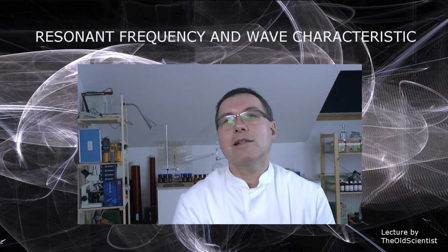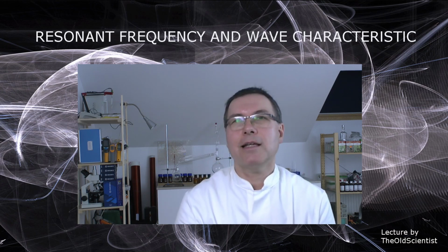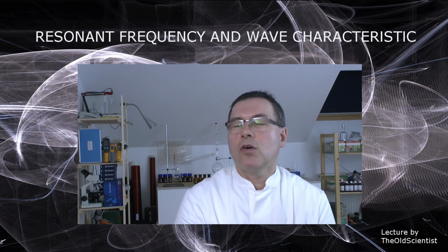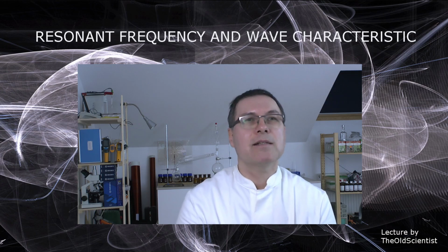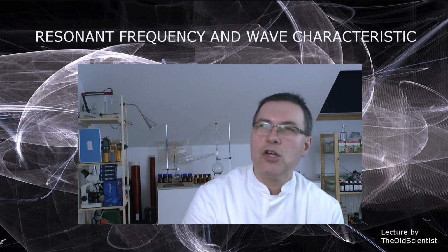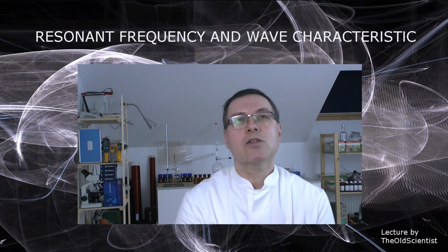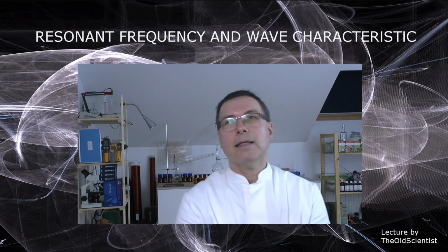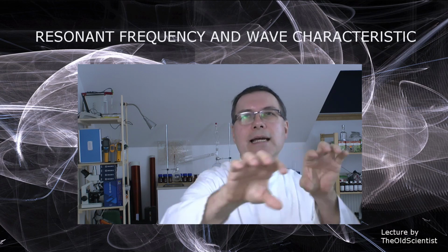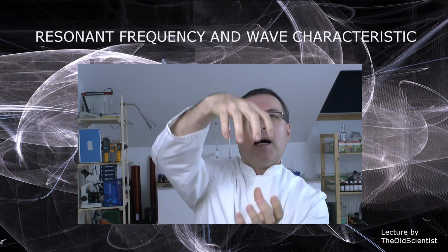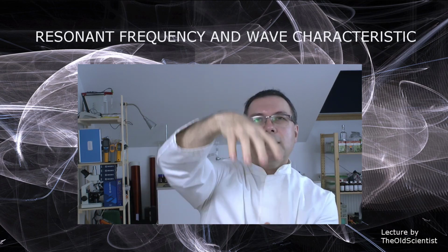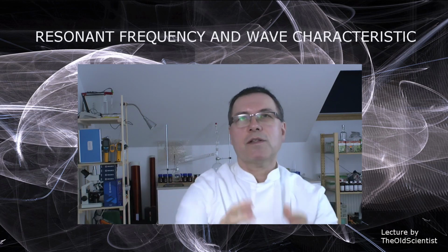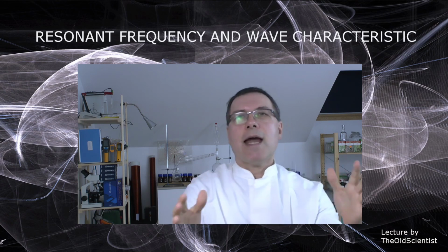The Pancake coil is a completely different subject, and I didn't use it. This is a question here from AR. So the Pancake coil is a completely different subject. Reason being is that the magnetic flux, and the orientation of the magnetic flux, is completely different to what happens here on a solenoid. Because rather than going in a length in and out, it expands in a vertical fashion. It doesn't expand horizontal, it expands vertical, and because of that, they don't interact in that fashion.